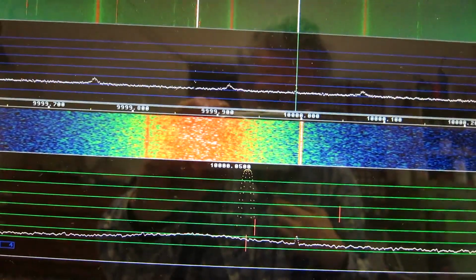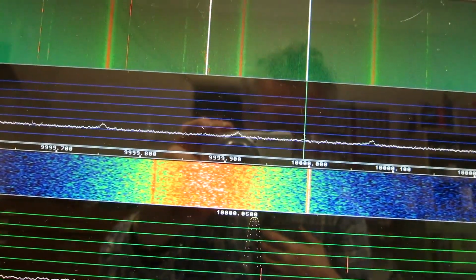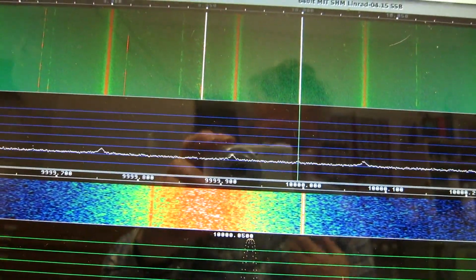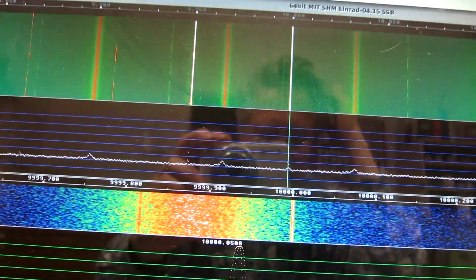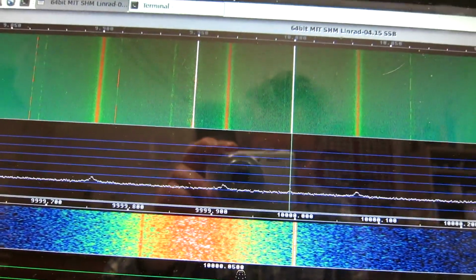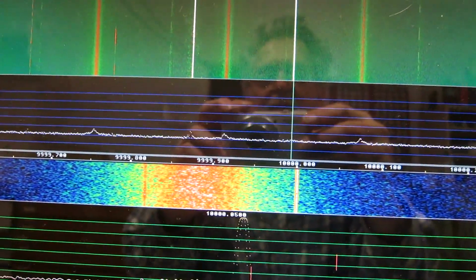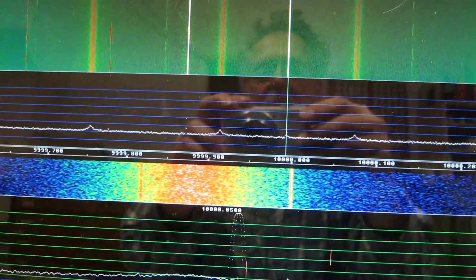On the average, plus and minus 50 Hz from the center, the level is minus 167.3, and that is 184.3 dB below a 17 dBm carrier on the input.